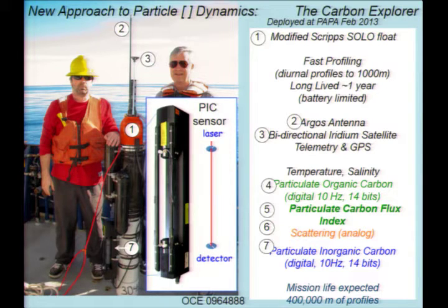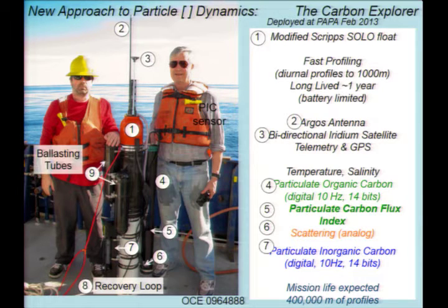The idea is that carbonate particles are birefringent, therefore they depolarize the plane of polarization of the beam, and those photons pass to the detector. The reason this sensor hasn't leapt into availability is that there's a big job involved in keeping 1,000,000-to-1 crossing efficiency polarizers crossed in a profiling mode. Wet Labs is about done with this problem now, and we're taking it out to sea in 2 weeks.